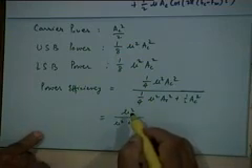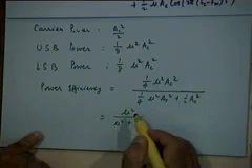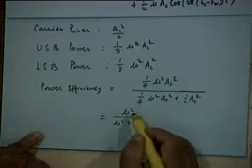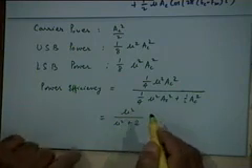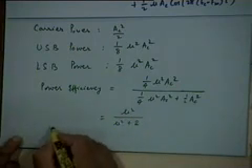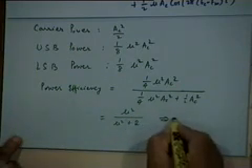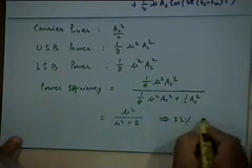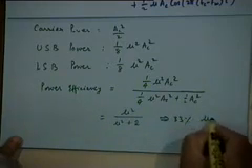That is the power efficiency you will have for a modulation index of mu. And what is the best power efficiency you can have? It will be obtained by mu equal to 1, right. And what is the power efficiency there? So, 33% approximately for mu equal to 1.